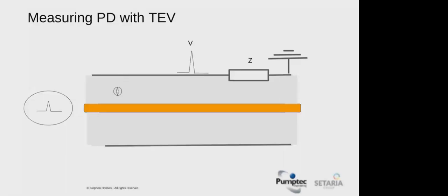So luckily, when there's a current kick in the conductor, there's a similar equal and opposite kick on the surrounding metalwork. Remember, all this is high frequencies now because the pulses have very high rise times, and so they're full of high frequencies. Also because they are full of high frequencies, that current has a distinct impedance between the point of measurement and true earth. It might only be an ohm or two, but it's enough to create a voltage spike, which we can measure more easily. How do we measure that voltage spike then, which we know as a transient earth voltage, TEV?